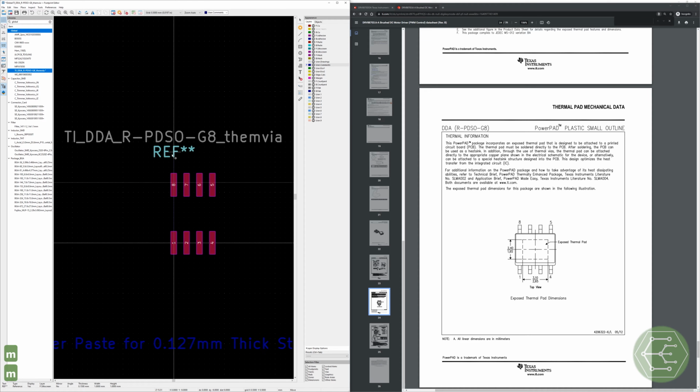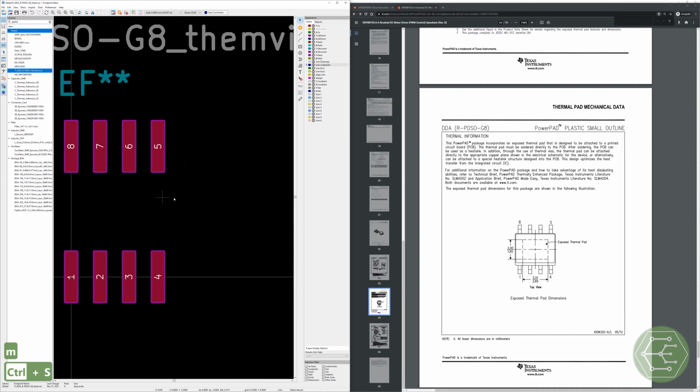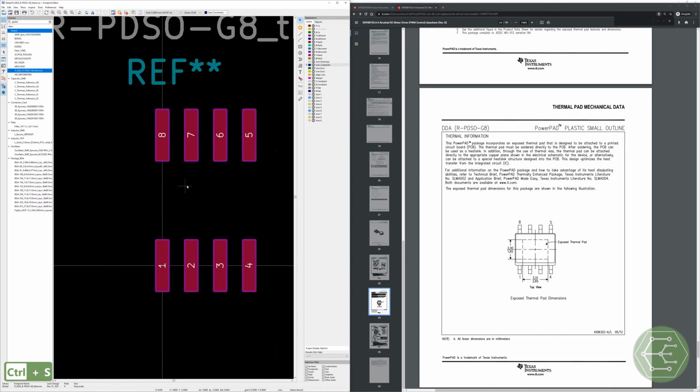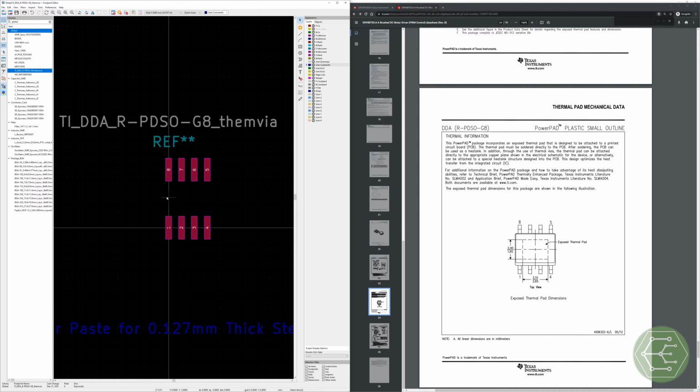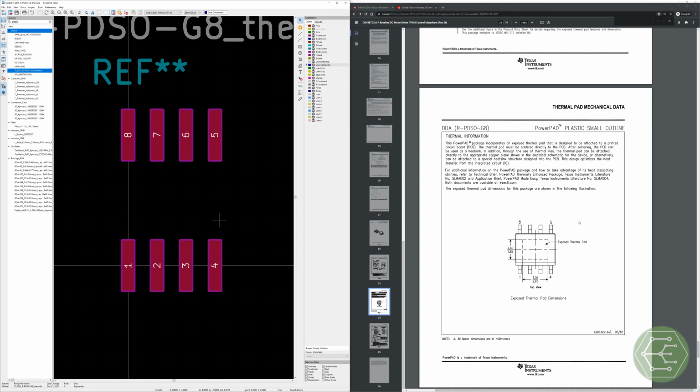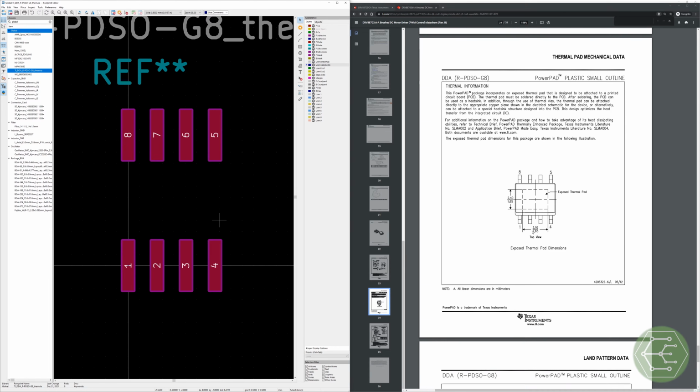So that's great. That just put in most of the hard work of getting your pin spacing correct, numbering it, and placing it all. That's part of why I love symbol creation in KiCad. I love that create pad array. I would hope every tool has it, but in my experience, they haven't all had that.